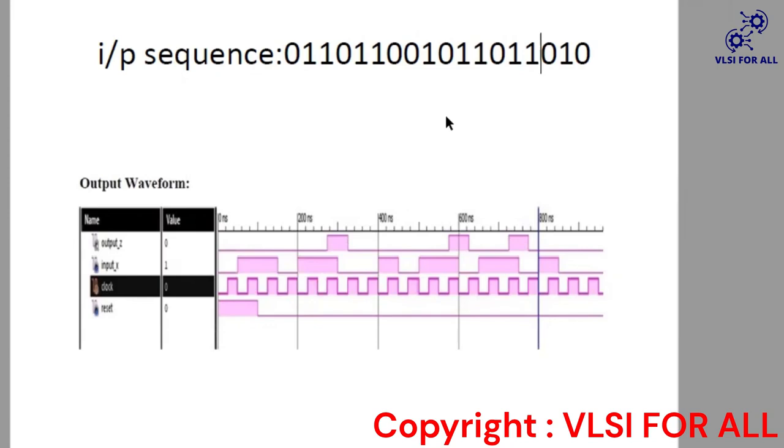So that's all for this video. In the next video, we will see the non-overlapping case. I will give you a brief summary for the non-overlapping case in this video also. What will happen for that same input in the non-overlapping case? It will detect only this first sequence and this second sequence. It will not detect the further sequence because it will not reuse this bit from the previous sequence.